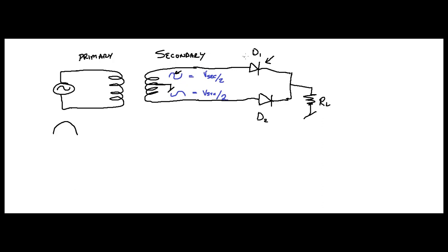This voltage is going to go through your diode, through your load resistor to ground. Got it? So your output is basically going to look like this. Got it? Now, you know there's a diode drop here like the other one, so your peak here is going to be 0.7 volts less than your V secondary over 2. We'll talk more about that later.